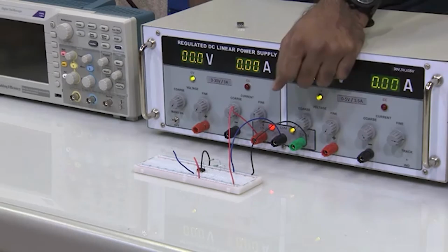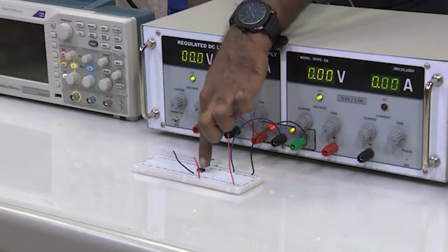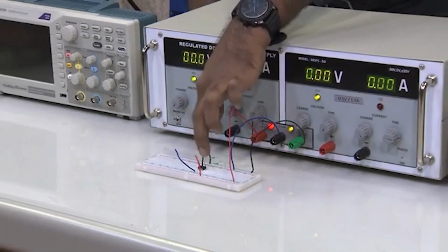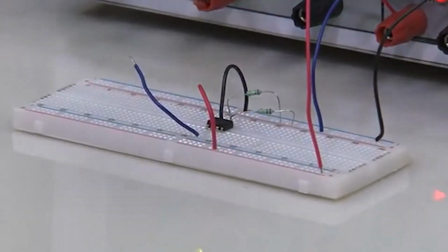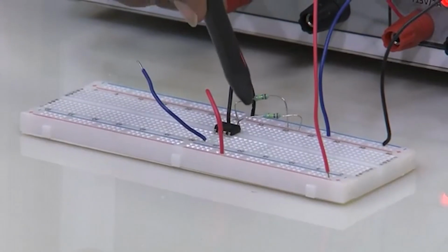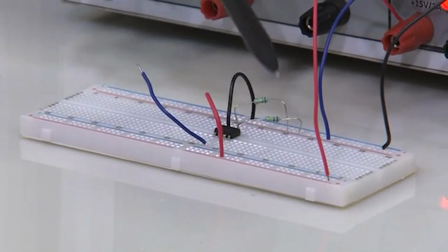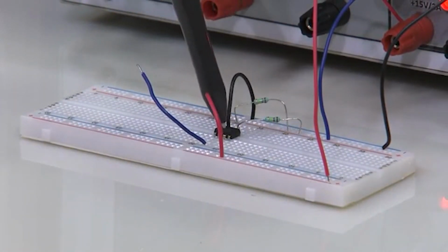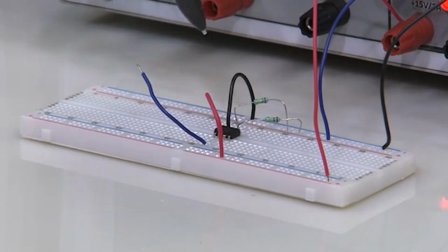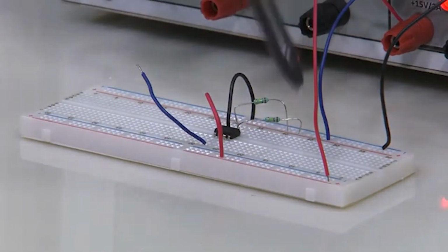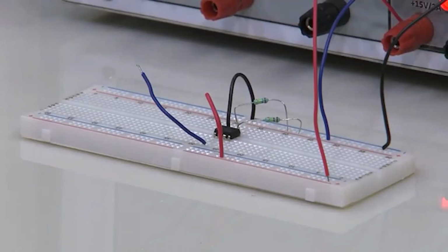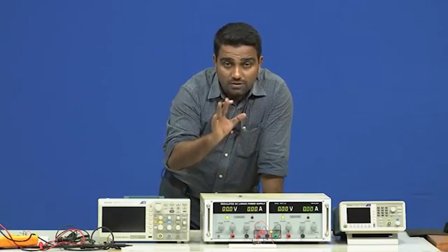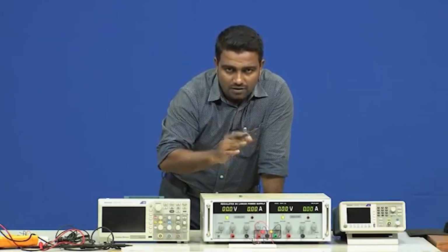So, here what is there? There is an integrated circuit which is your operational amplifier, and there are two resistors, 220K each. Now, we have applied the bias voltage to the operational amplifier. How do we apply bias voltage? By applying plus 15 and minus 15 across pins 7 and 4, where 7 is plus VCC and 4 is minus VCC or